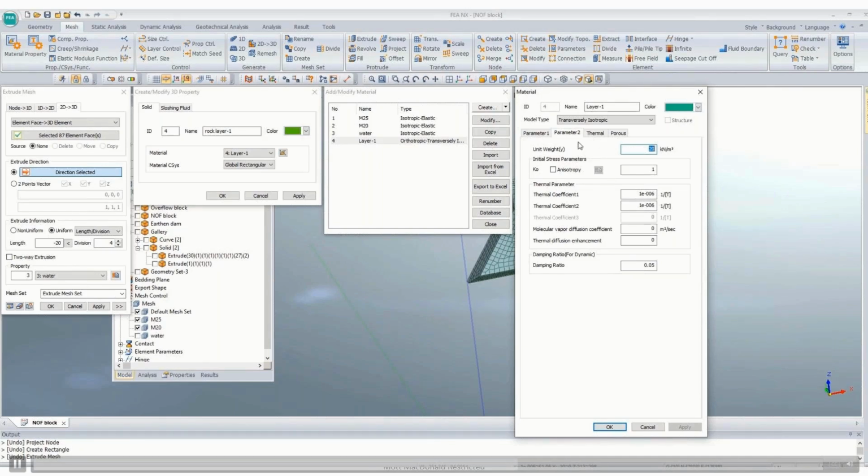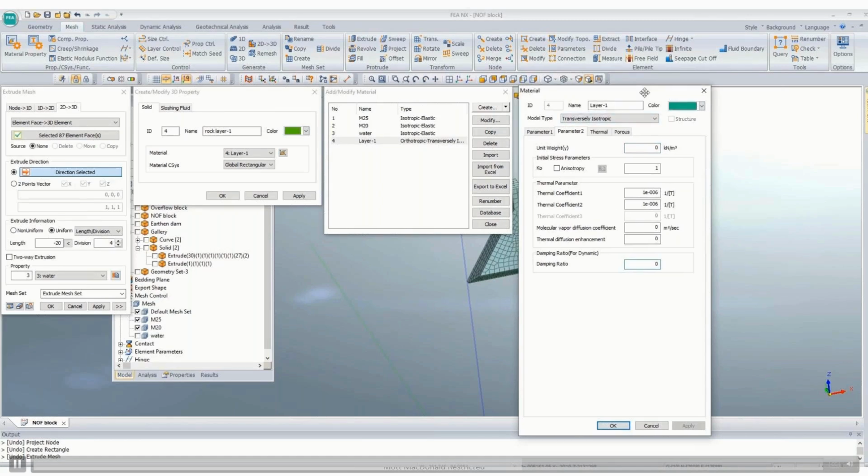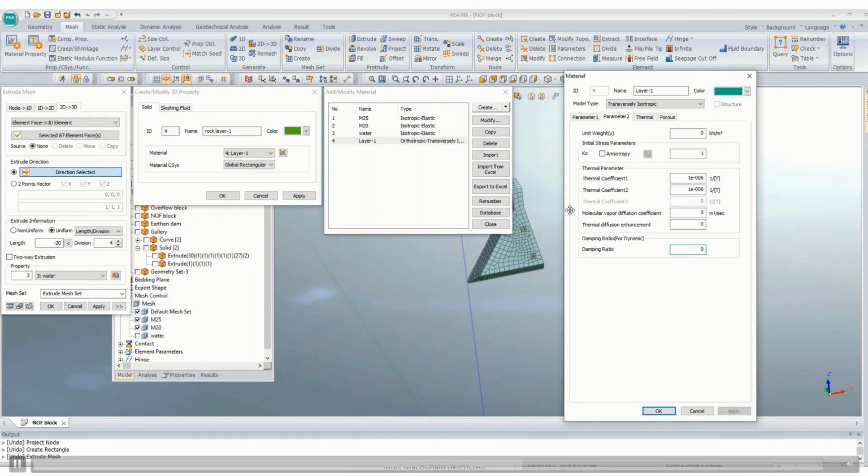Anyways, in USACE Engineering Manual 6051 it is mentioned that we can model a dampless, massless foundation to get the maximum response at the structure. So this is the simplistic approach, and I'll be using that only. I'll put 0 here and without any damping. In the code, it is mentioned that we should start with the simplistic pseudostatic seismic coefficient method analysis, which I have already done, before moving forward to the more refined, sophisticated analysis. So I'll be using dampless and massless foundation here, layer 1.